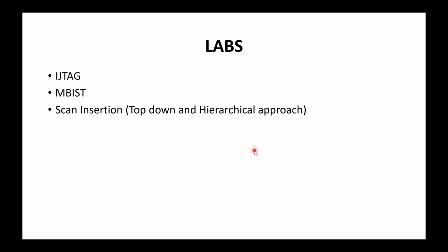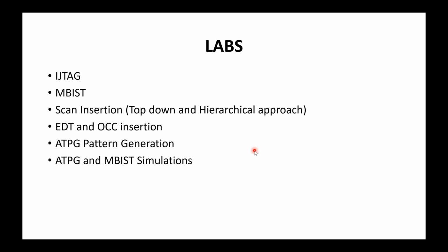Then EDT OCC insertion: EDT is compression, and OCC, the on-chip clock controller, and the need for it will be discussed during the course. Then automatic test pattern generation, and finally simulations. Patterns generated during MBIST and ATPG will both be simulated.